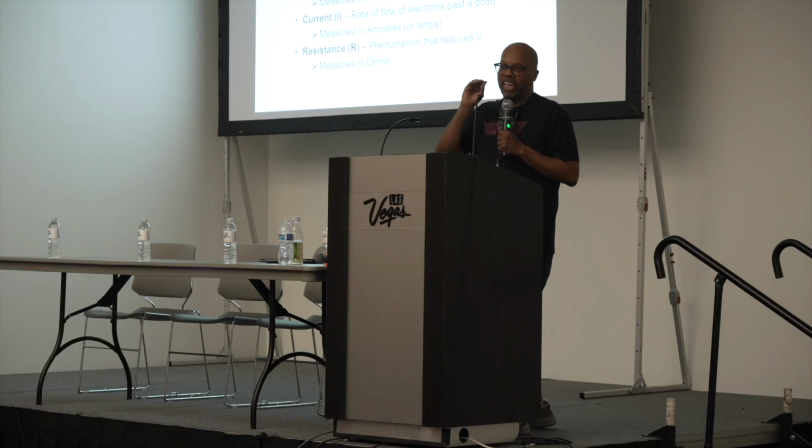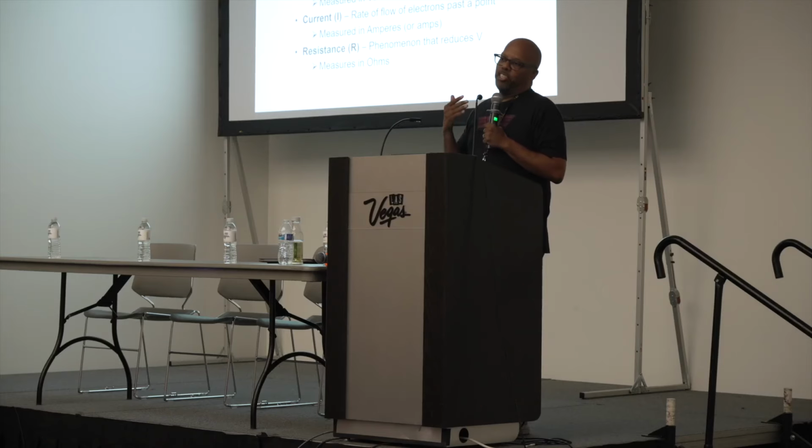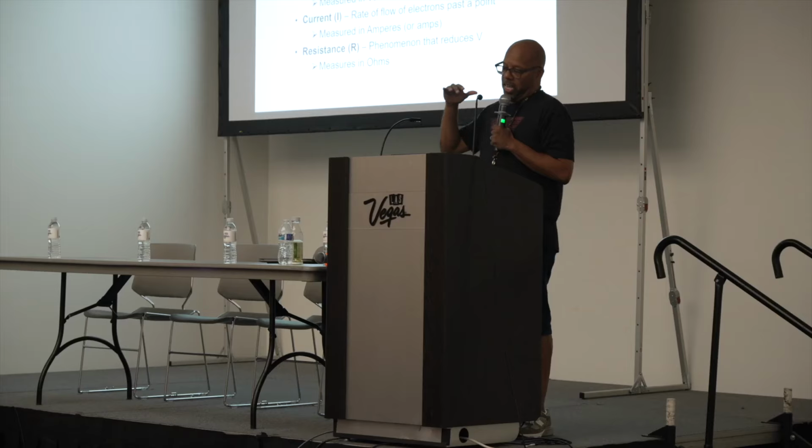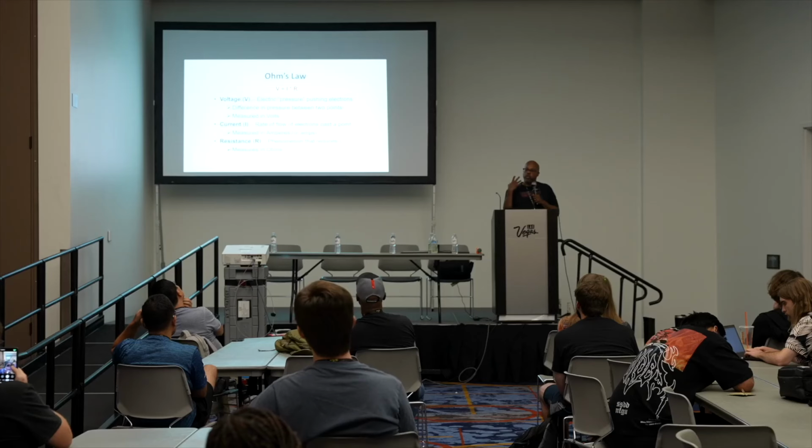So, Ohm's law. This is really simple, so don't be intimidated. You may remember this from physics. V equals IR. Voltage is like the electric pressure, I is the current, and R is the resistance. Think of this like water going through pipes. It's exactly the same thing. The pump is like the battery, the voltage source.